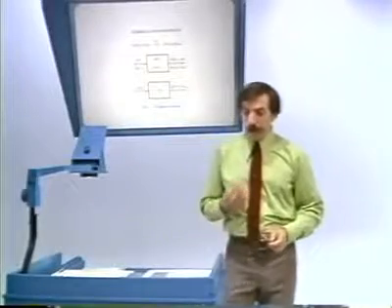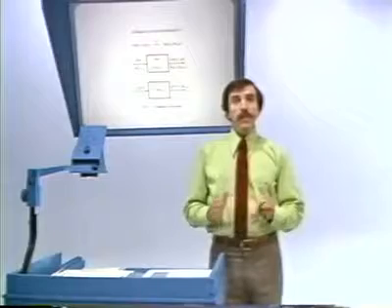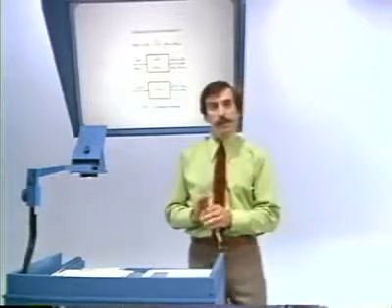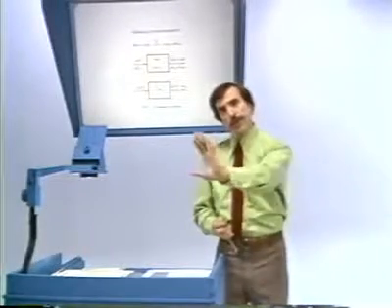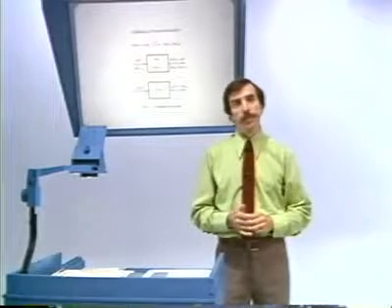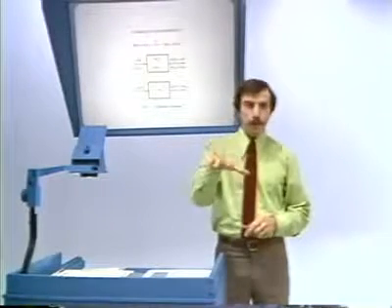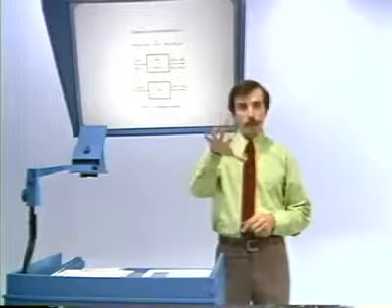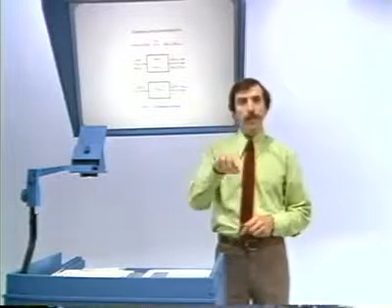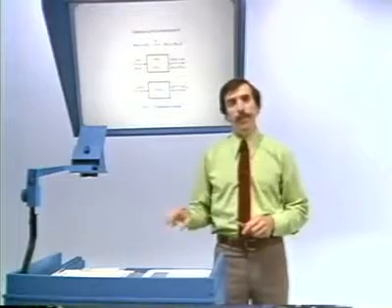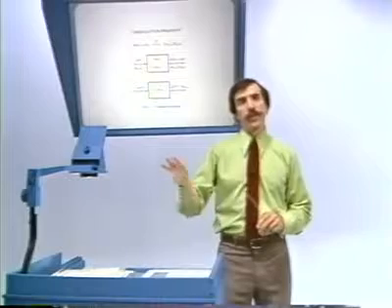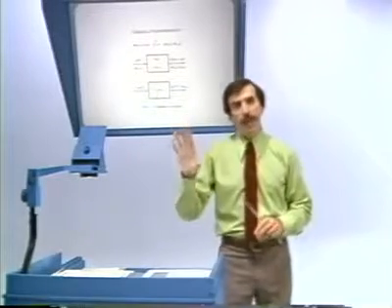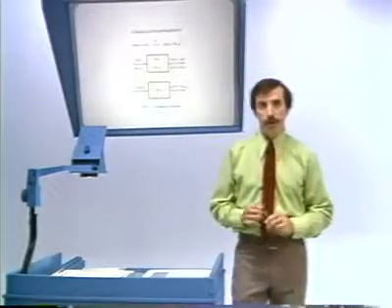So, in fact, the convolution property simply tells us that in terms of a decomposition of the signal in terms of complex exponentials, as we push that signal through a linear time invariant system, we're separately multiplying by the frequency response the amplitudes of the exponential components used to build the input, and that sum in turn is the decomposition of the output in terms of complex exponentials.